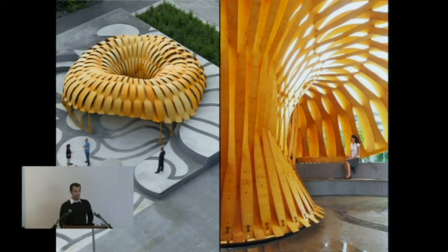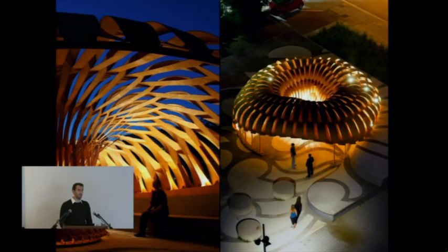The pavilion's final equilibrium state unfolds a unique architectural space, while at the same time being extremely efficient with the employed material resources. The combination of the pre-stress that results from the elastic bending in the assembly process and the morphological differentiation of the joint locations allows using only extremely thin plywood strips. In fact, the entire structure, which has a diameter of more than 12 meters, could be constructed using birch plywood with a thickness of only 6.5 millimeters.